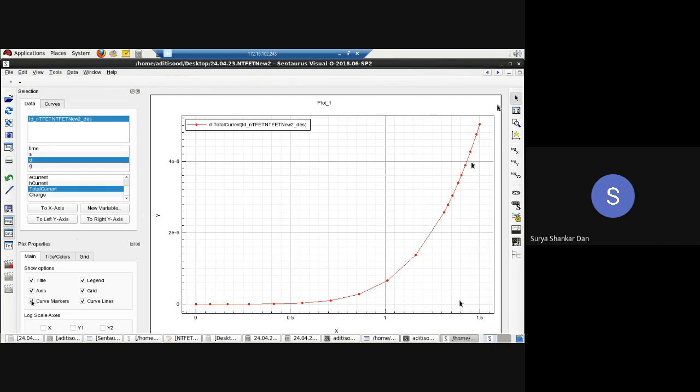Now, what you are going to do, you are simply going to change the oxide thickness. What does it mean? That means you have to fabricate a whole new device with a different oxide thickness, which is not possible so easily. So, if you want to actually learn the device, you should use simulations very well. Simulations then make sense of the data.